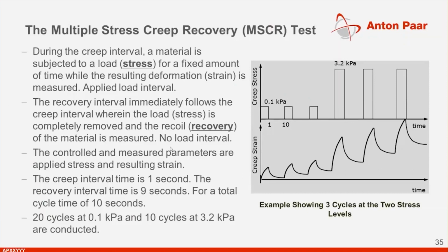This gives us the possibility to measure the relaxation of the material for 0.1 kilopascal. 20 cycles are applied, but again, only the last 10 cycles are used for calculation, and the first 10 cycles are to ensure a homogeneous sample behavior.